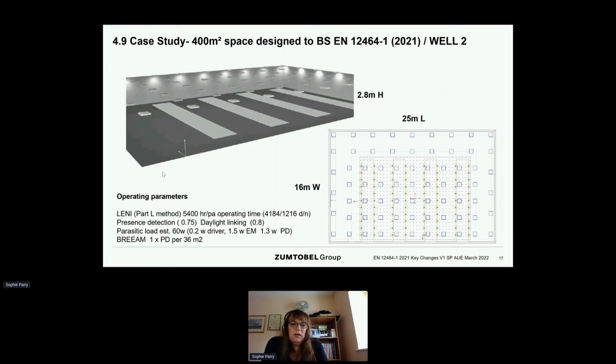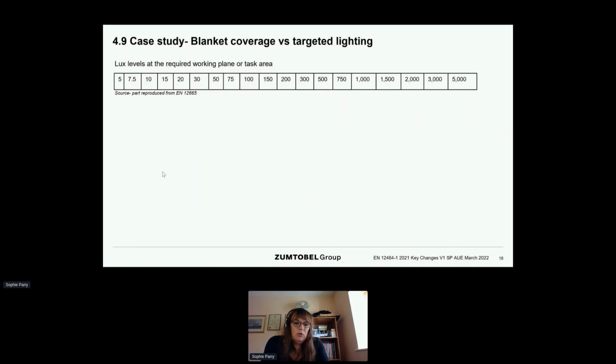all of our luminaires in the space in a typical popular configuration that might be required by a client, and also in some cases look at the melanopic content of some of the suitable luminaires for a lecture theatre or an office space, for WELL specified projects. So we tested about 30 luminaires and probably did about 5 tests per luminaire in slightly different configurations in the same model. So they were all tested to the same standard, just to see what would happen as this new standard came to fruition. And we did draw some conclusions.